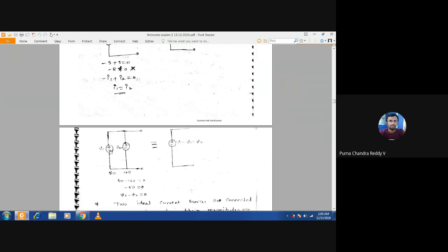Okay, here V1 is equal to V2. Whenever we are connecting voltage sources in parallel, the value of those voltage sources must be the same. Okay. So student, if you change the minus to plus, this should be minus V2. Means if this is plus minus with 5 volts, here you have to have plus minus with 5 volts or minus plus with minus 5 volts. Same or not?